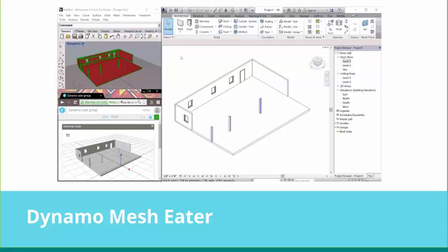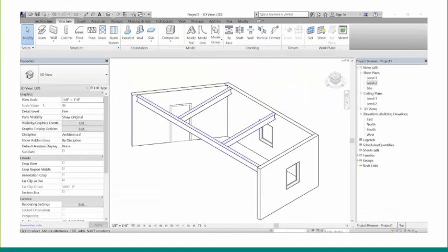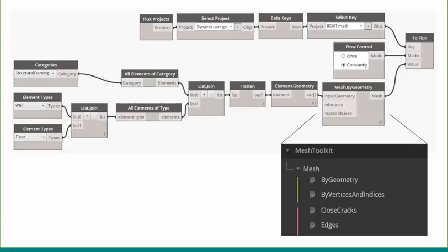And so here you can see a Revit model with a whole bunch of different geometries. On the bottom left, we can see that now showing up in Flux Live, and then also represented in Rhino on the top left. So I can draw something in Revit, just using all the native components. I'll use my Dynamo graph to collect up the geometry from these different components, and then using the mesh toolkit, which I download off the package manager, just send the mesh out to Flux.